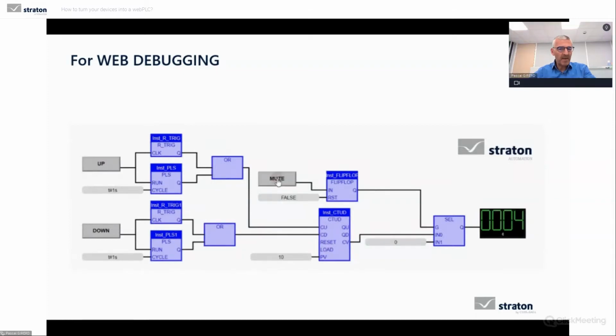That can be Apache or LightTPD. Then you make remote diagnostics of the execution of your program, your application. You see this IEC 61131 view where you can see variables evolving. You can also change their values. You see it changing in front of you.